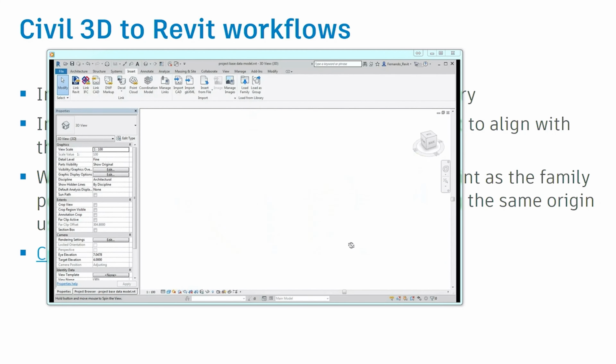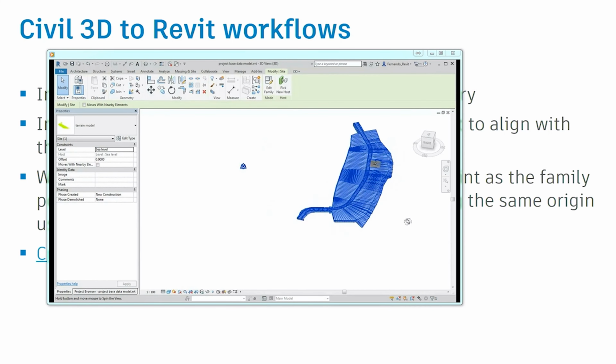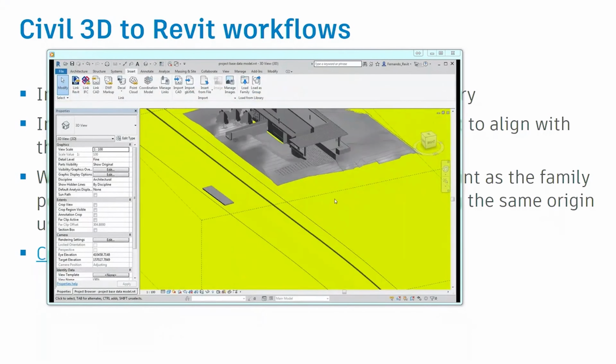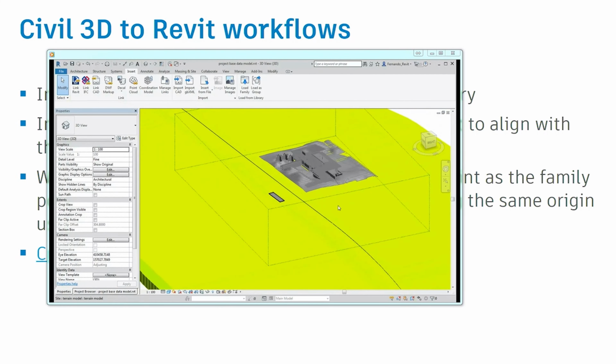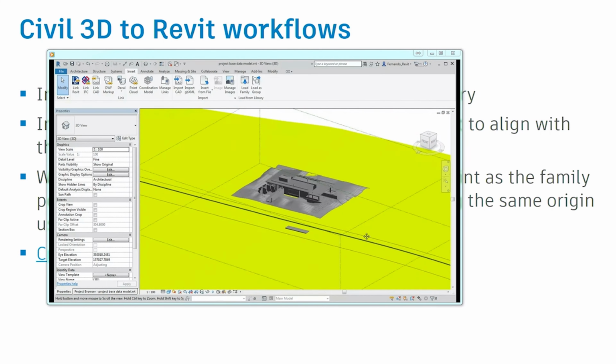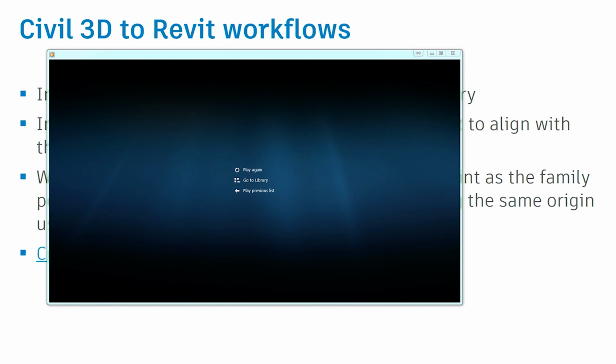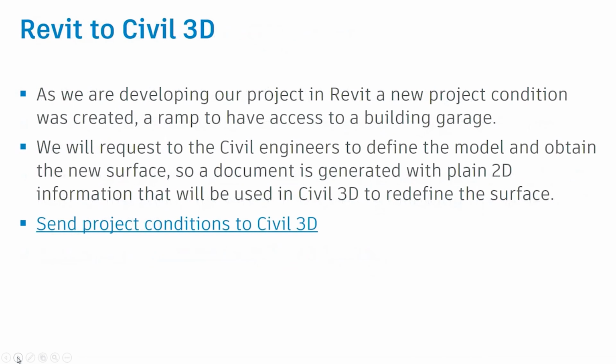Lucia gave me this main surface, but I had the road, pavement, the curbs, the bicycle path, everything is there. So I'm bringing these components into Revit. I can bring a roundabout, the subcomponents of a roundabout, as solids piece by piece and put it here. Sometimes for the roads we can make the intersections. We don't need to bring the full road like we had in this project. So it could look a little crazy sometimes why we do this, but it's the only way to be able to have this kind of BIM components in an environment outside Civil 3D.